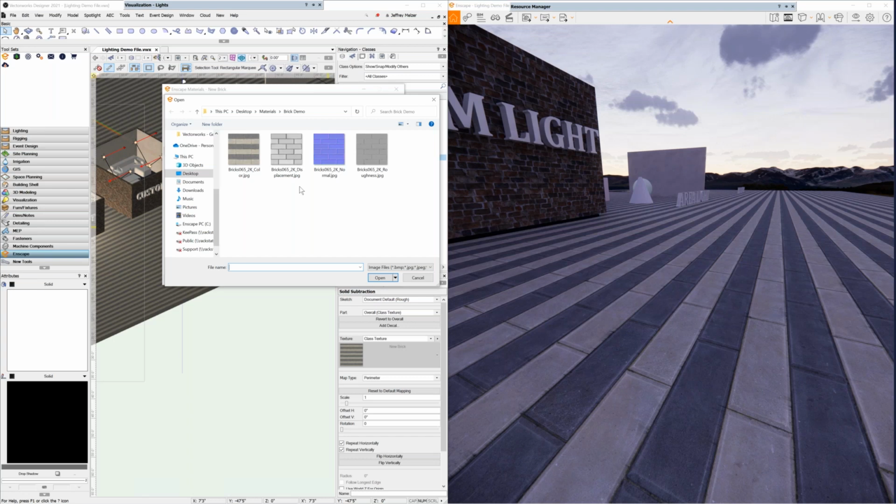A bump map is kind of your oldest style of maps that were around. They work. They're the workhorse map. However, there's some other options that you can get into. Normal maps nowadays take actually into account the RGB values, and those, depending on how you set it up on the map, will actually give you the different bumps and different offset of materials.